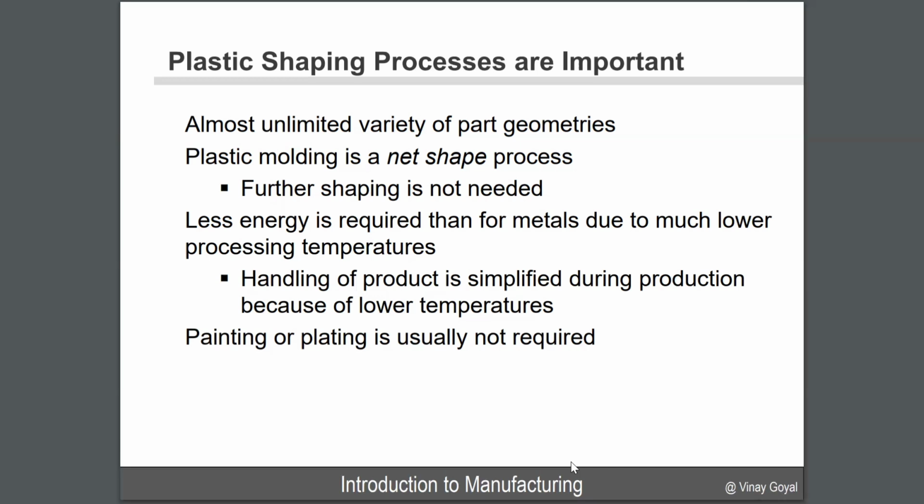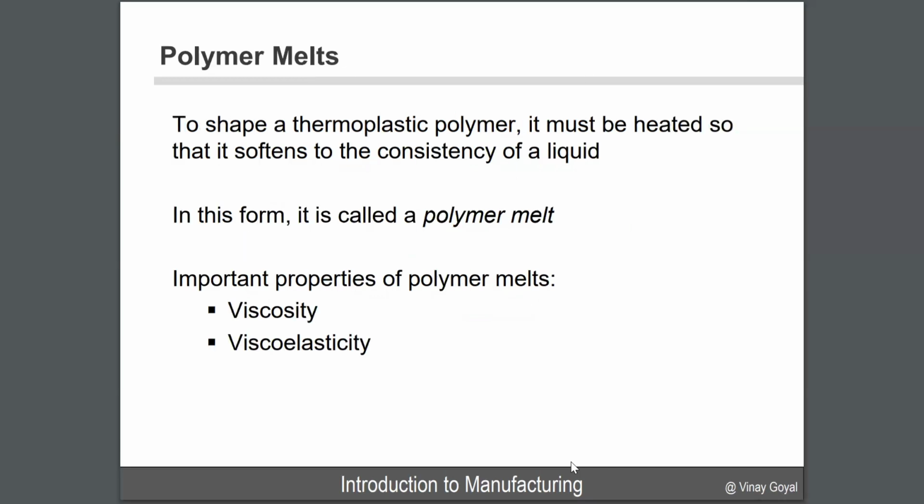The other cool thing about polymers in general is that you don't have to do additional treatment on the surface, like painting or plating. In some cases, though, it's very nice to have that. For example, in manufacturing, if I have a part that's critical for flight conditions and it's polymeric, perhaps painting it white is very helpful, because the white paint becomes an indicator of something that may have touched it and damaged it. So sometimes paint is used as a protective measure to give you an indication of a problem that may have occurred.